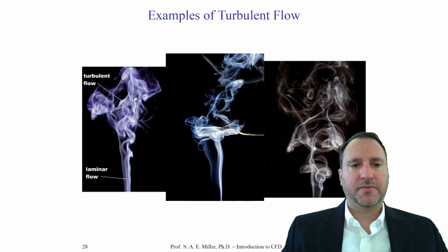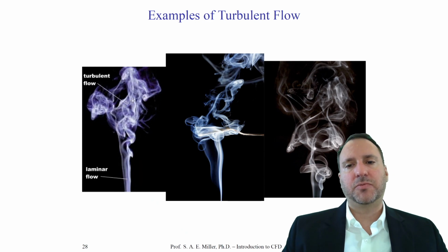Now, if I go into this flow and put a little probe in it to measure velocity, I could find the energy spectrum, and you would see it have somewhat of a spectrum which, like Kolmogorov predicted. It's very interesting that happens. We can put a spoon in the smoke stream and see the smoke come up and go around the spoon, and it forms this turbulent wake. So this is another visualization of turbulence.